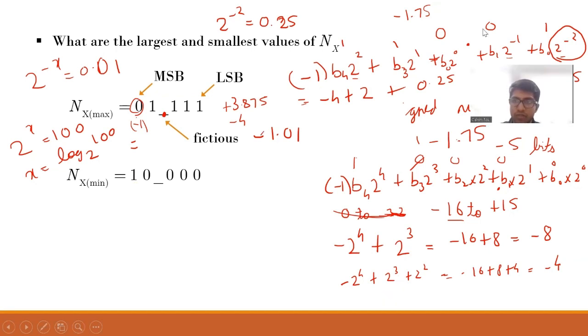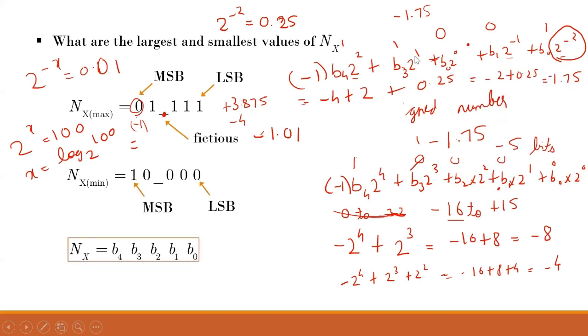Okay, are you guys able to see my screen? Yes. Here in this case, it is 0, 1 underscore 1, the example that we have taken. Here the first bit is 1, that is representing -2, and then the second bit is 1 into 2 to the power 0, and then plus 1 into 2 to the power minus 1.